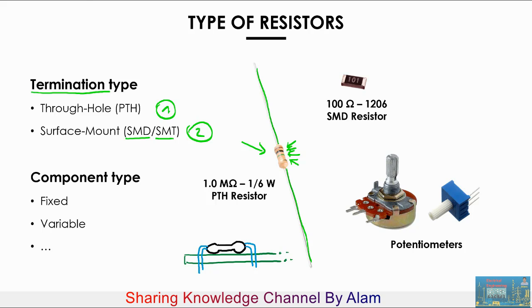Then what you do is that you take your soldering iron and you solder the other side. Obviously the leads normally are much longer than this, so they continue going, but after you solder them, you just trim them, because you don't want to have leads hanging on the other side of the board, which are not doing anything anyway. So that's how you assemble it, and that's how we justify the name of this category of